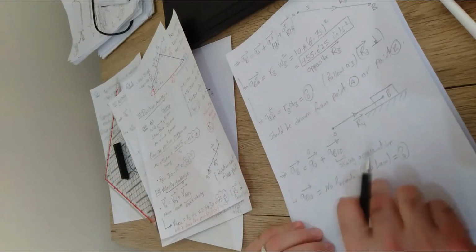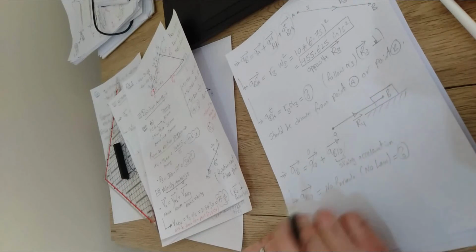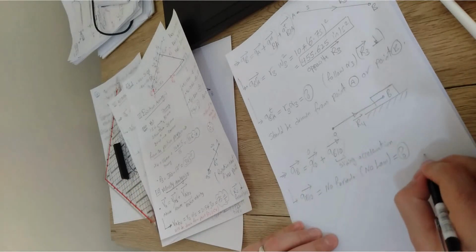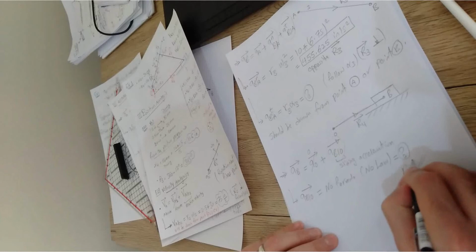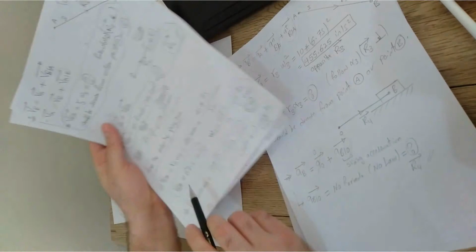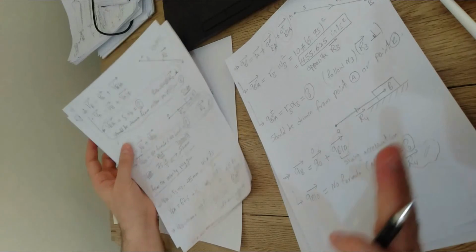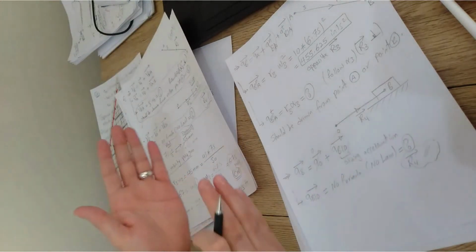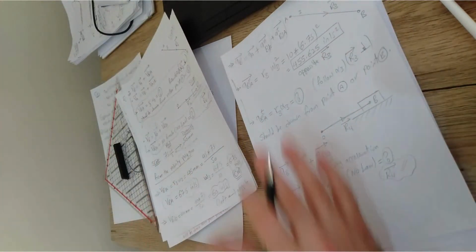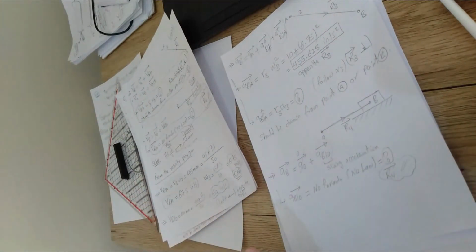But what about the direction of this sliding acceleration? Again, it should be parallel to the R4 vector, typically the same as we did for the velocity part. We wrote that it is parallel to the R4. Parallel to the R4, again, means that it is not necessarily in the same direction as R4 or opposite direction to the R4. It depends. It depends on the data, and after we draw, we can identify the exact direction of this acceleration.